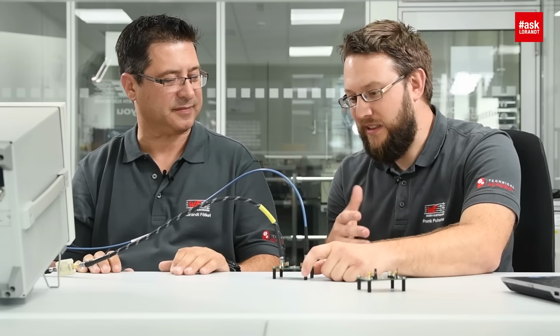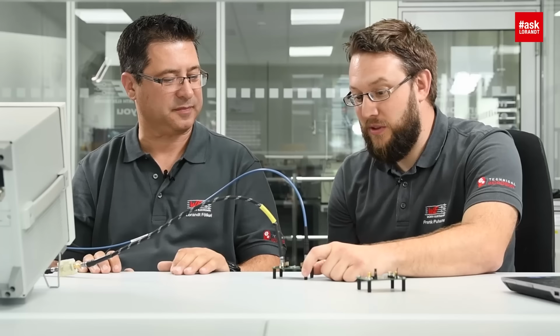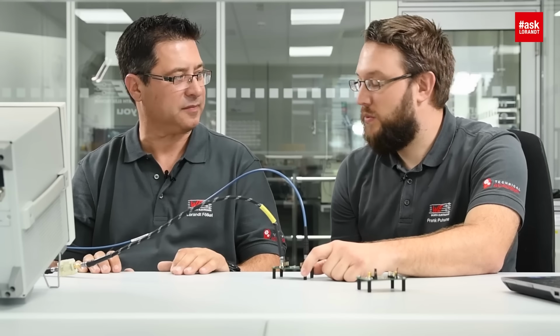So when you have high capacitance values, you have to check the DC bias curves. Absolutely. Or the customer can do it with our expert tools, so we provide the data. This is really necessary to check.